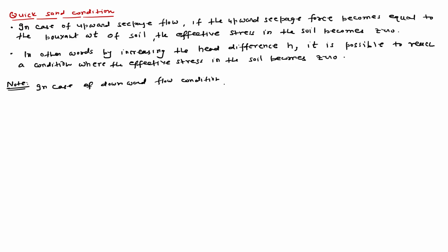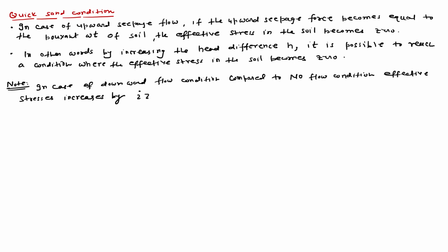In case of downward flow condition compared to no flow condition, effective stress increases by i z gamma w.